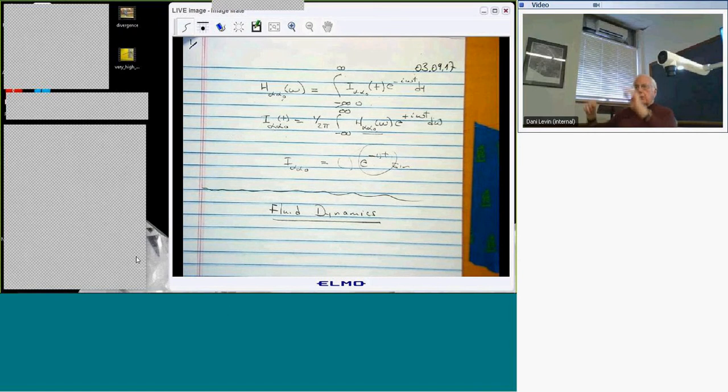Okay. Now, you take those equations I just mentioned and boil them down, and you assume that there's a mean flow, which is uniform. This is an approximation, right? But think of a wind tunnel. There's a mean flow with a mean velocity, and it also has a mean temperature and a mean pressure and a mean density. And then you assume that if I put an object in there, like a wing, whether it's moving or not, it gives rise to a small change in all those parameters, right?